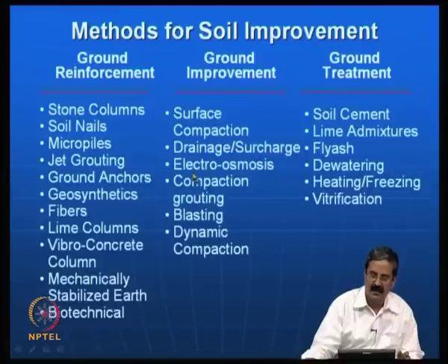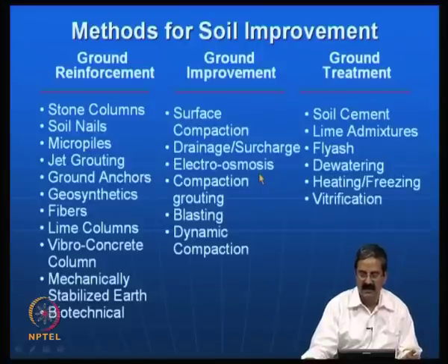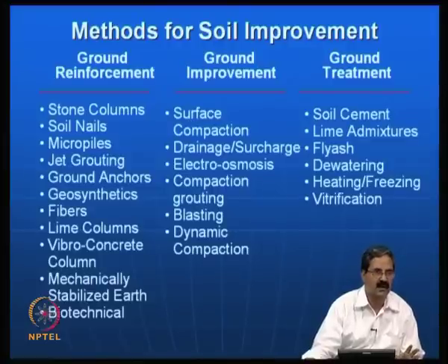In some cases in clays, sometimes we use electroosmosis. You must have heard of electroosmosis in basic geomechanics classes, where clay particles are negatively charged. If you really want to remove the water, electroosmosis is one thing that can be effectively used, because there are two types of water. One is pore water, and then there is water that is adsorbed to the clay surfaces. So, if you want to handle them properly together, electroosmosis combined with drainage is an excellent option.